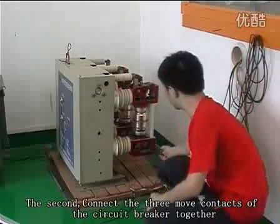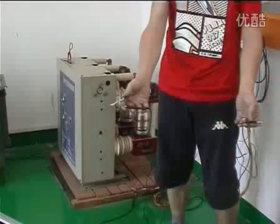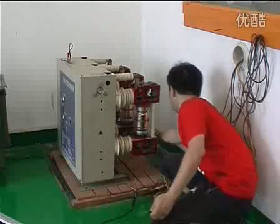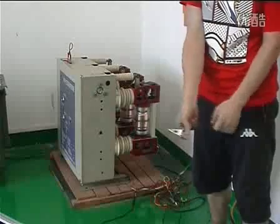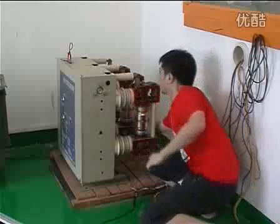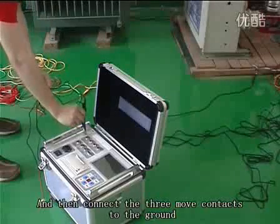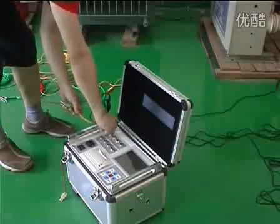The second, connect the 3 moving contacts of the circuit breaker together, and then connect the 3 moving contacts to the ground. The third, connect the contact signal detector unit.